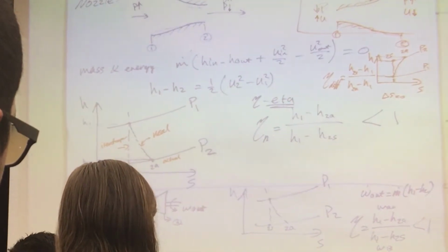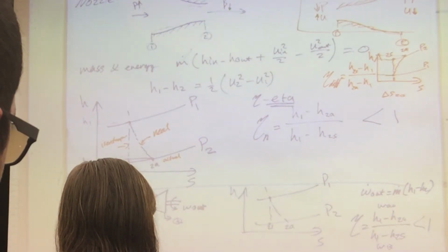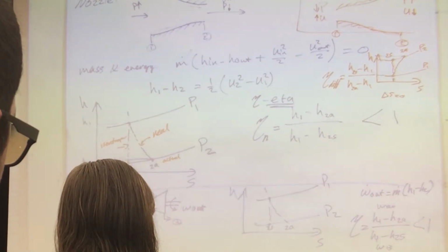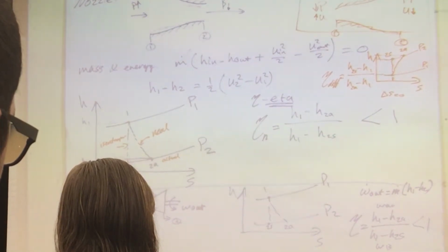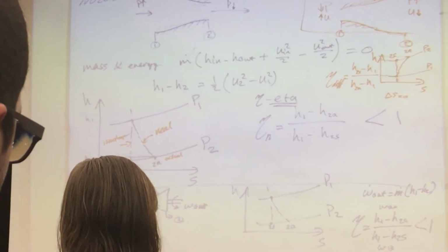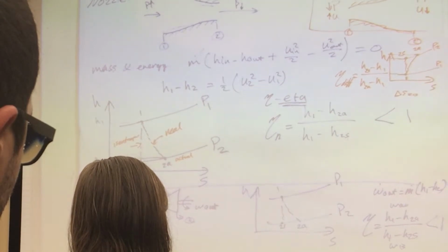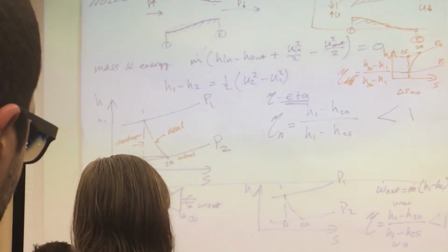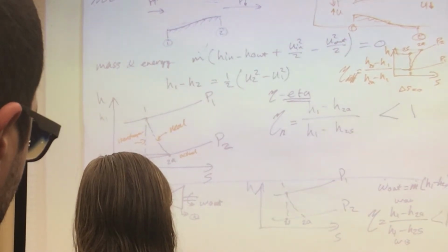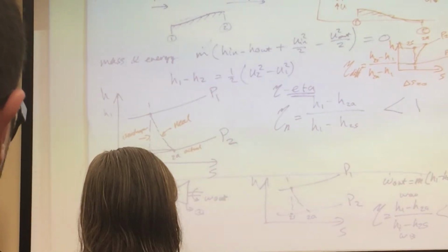We're trying to slow the flow and get higher pressure through the diffuser. So by doing that, the ideal situation will be to get the higher pressure at the minimal energy possible, which is your isentropic process. Versus the actual, well, you end up putting in more work in terms of flow work, in this case, which is enthalpy, to get to the same pressure level because of boundary layer effects, separations.